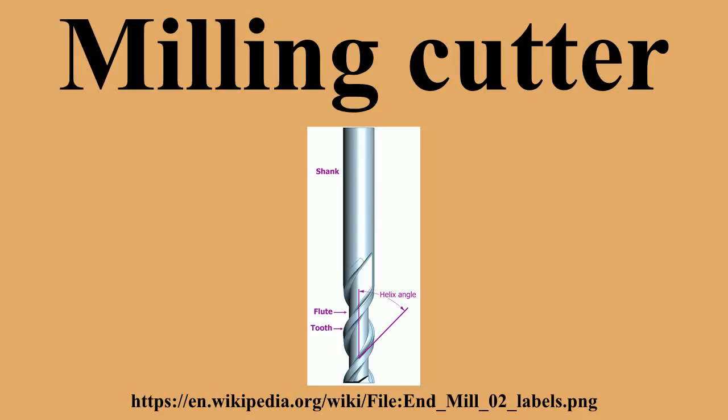Side and face cutter. The side and face cutter is designed with cutting teeth on its side as well as its circumference. They are made in varying diameters and widths depending on the application. The teeth on the side allow the cutter to make unbalanced cuts without deflecting the cutter, as would happen with a slitting saw slot cutter.